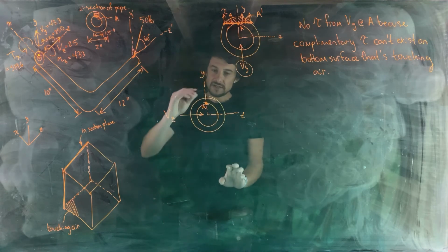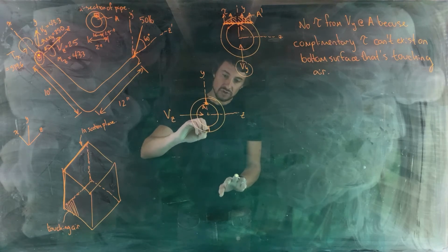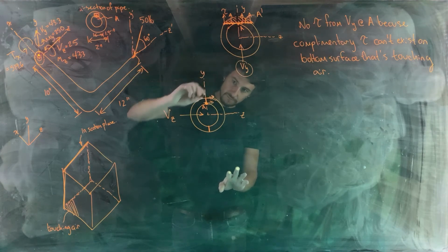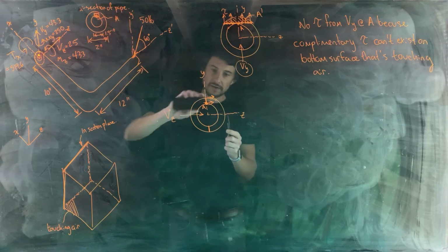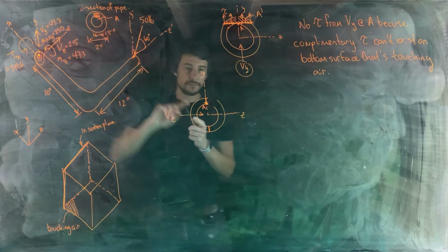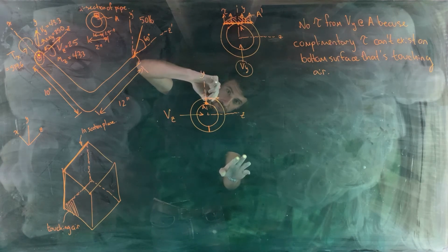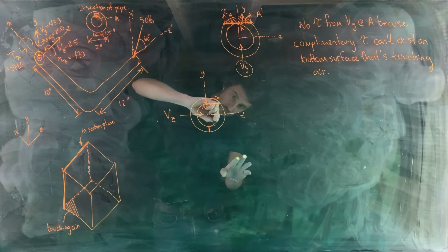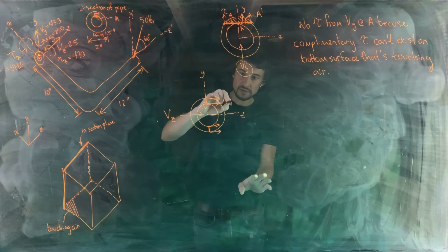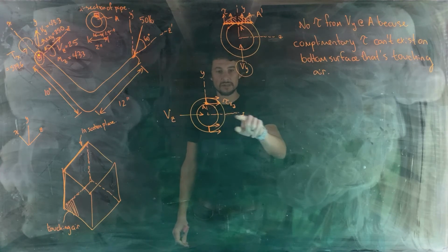So when we're thinking about the shear stress at A now, we're drawing a line that's perpendicular to the direction of VZ passing through point A. So shear stress is going to exist on these two lines that I've drawn. It's going to be oriented in the direction of VZ, parallel to the Z axis. Right, so all those share the same value, tau VZ. So at point A, there's a shear stress, tau VZ, that points in the positive Z direction.